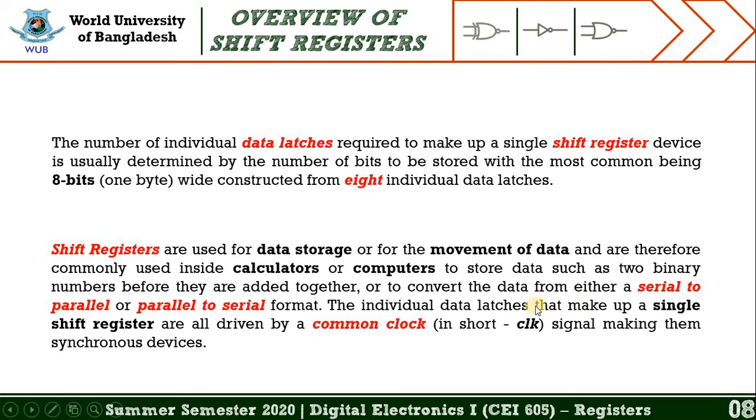The individual data latches that make up a single shift register are all driven by a common clock, known in short as CLK, signal, making them synchronous devices. Now time has come to explore how to design a 3-bit serial in, serial out. So let's move into the next slide to explore the design.